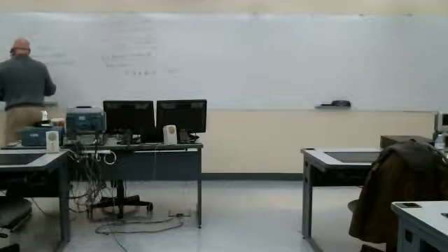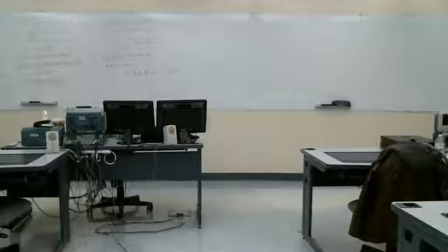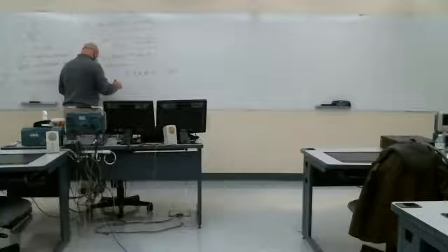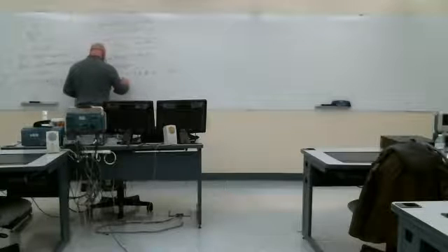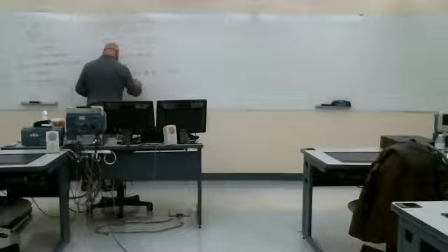Okay. Now, it doesn't matter how small this gap is here, Faraday's law now indicates that if we've got a time varying magnetic field, so that's correct for when there's no time variation. But if we've got a time varying magnetic field or a time varying flux, as we go around this loop, we're getting a voltage here. We can make that gap arbitrarily small. So Faraday's law is correct for a time varying field.